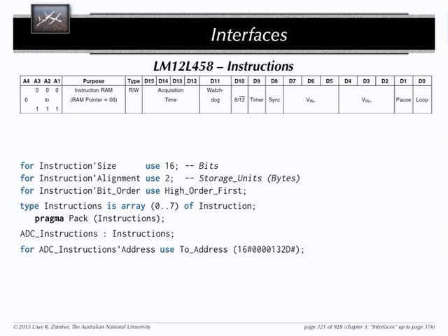Right? Now you distracted me. Read-write, exactly. What happens if my device can actually write to that? And how do you handle this from a higher level programming language? One thing which you will see in the interfaces which you will be using is that those registers which can be written from the device from the outside are marked as volatile in your compiler environment. What does that mean? It disables some kind of optimizations, doesn't it?